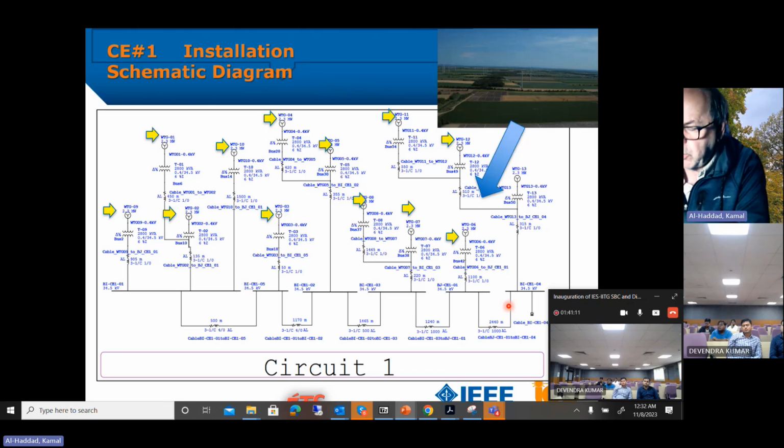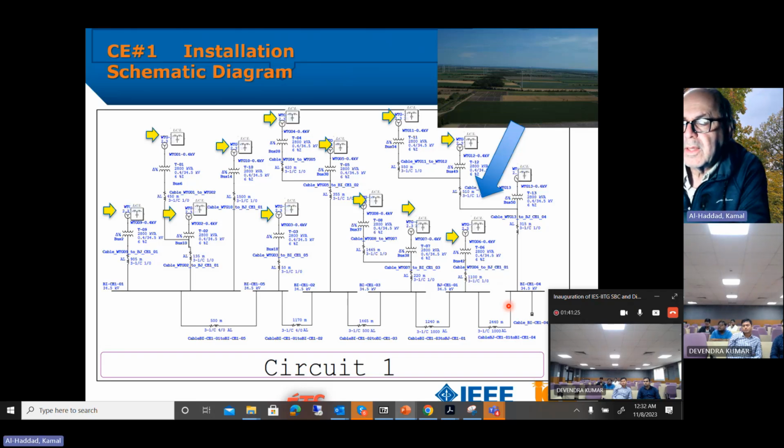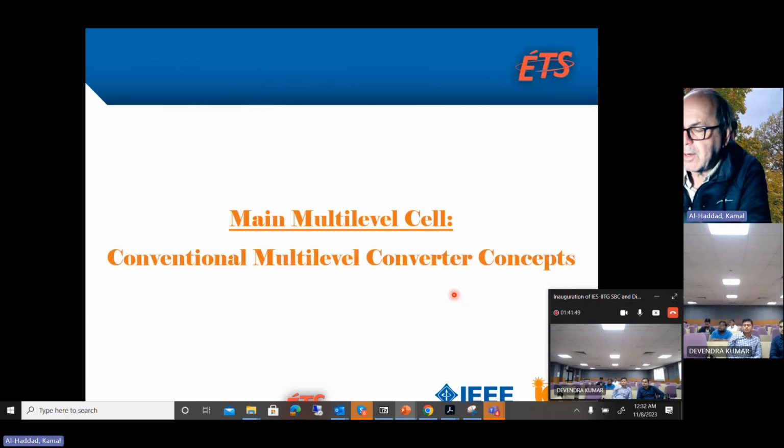So here is the question. If I do this, look at all those wind turbines that have filters: they will be removed. I won't need those filters. Look at the number of filters that I am using here. If I don't use these filters, I will have a very stable network with transformers and cables. This is a 100% stable network, and I will never lose control of the wind turbine. And you cannot imagine the number of faults those wind turbines go through.